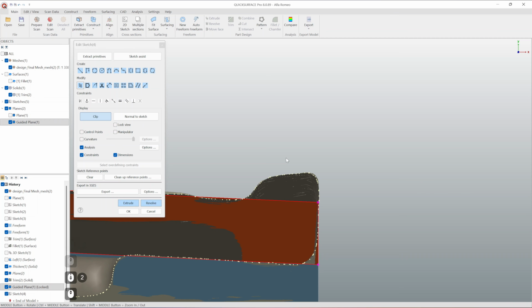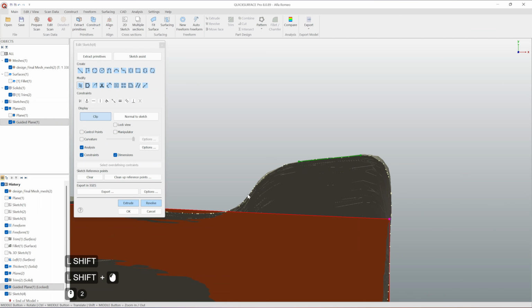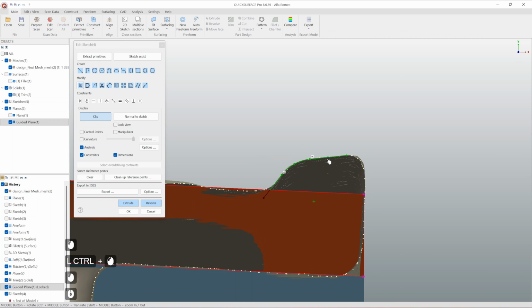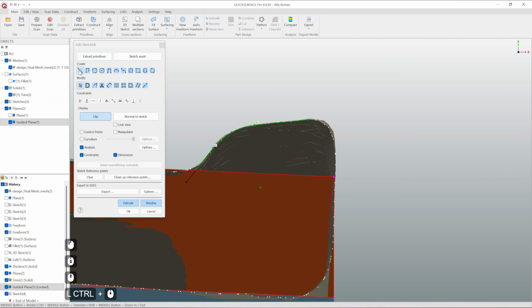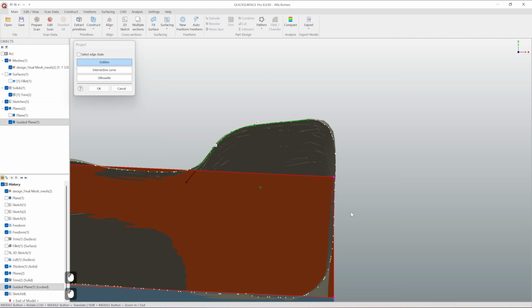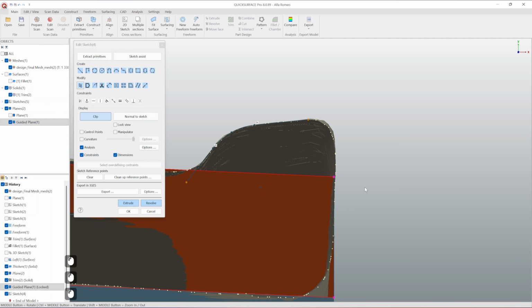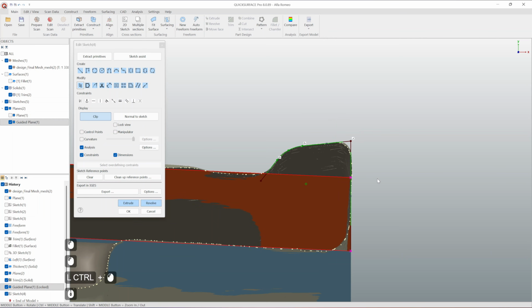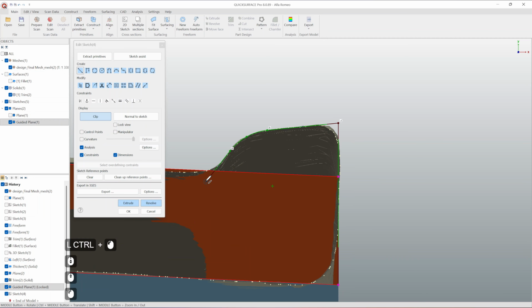And in this case, it would be, say we can fit entity here as well. Let's intersect them. Probably add automatic fillet. After that, I want to copy this edge here, just extend it, intersect, and let's just close.